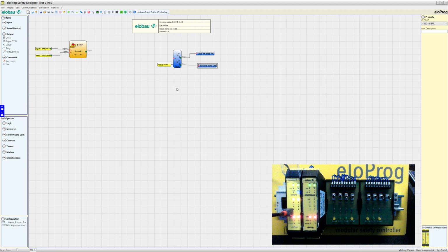So it's very important to choose and to wire this input. You can route a 24-volt signal over a normally closed contact of your contactors or valves and bring it here into pin 7. And if you connect input to output, this output would start immediately if 24 volts are applied. And if a contactor is sticking, it always sticks in the operated mode. So this input can't be applied with 24 volts and this output wouldn't start. That's the feedback function.